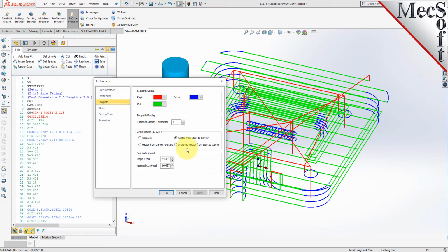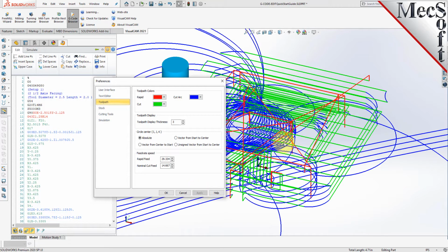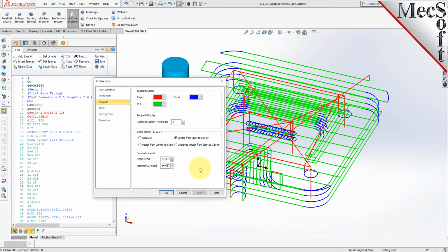So what we're doing here is we're just matching what's in the G-code file so that they display properly. If you see this on your controller, you need to go back into the CAM module and adjust your IJK format settings in the post-process generator to match what your machine controller is expecting to see. Okay, let's continue.